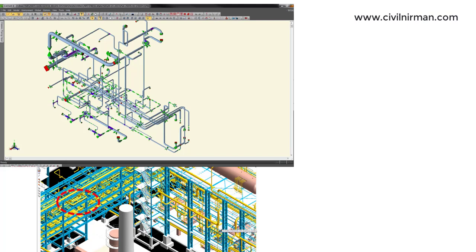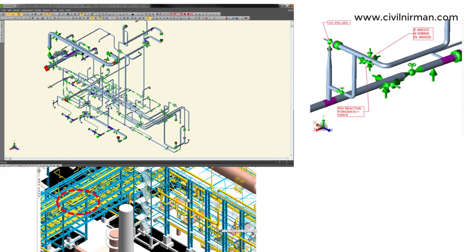Now let me just give you a snap over here. Let's say we have one detailing. So piping, what do they basically do? If I consider a small portion from this, in the Caesar software you will get certain information related to your pipe supports. See, we will support all those pipes on our pipe racks or in the shelter part, so we need to support these pipes with respect to their pipe support category, whether it is anchor, simple support, or the guide support, right? And based on that stress analysis, piping will provide you the detailing related to that particular junction.